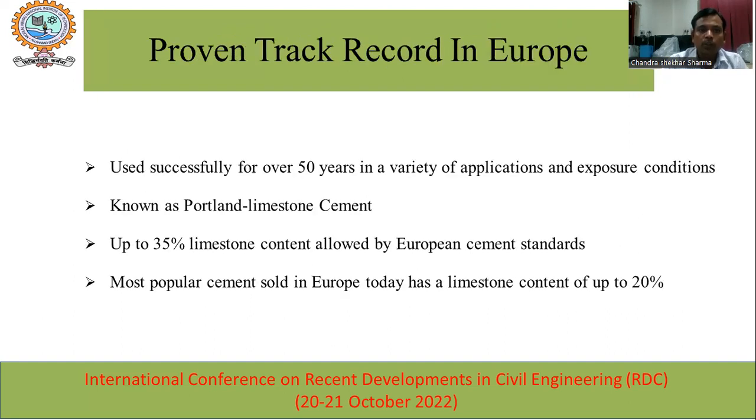Track record in Europe: PLC, known as Portland limestone cement, has been used successfully for over 15 years in a variety of applications and exposure conditions. Up to 35% limestone content is allowed by the European cement standard. The most popular cement sold in Europe today has a limestone content of up to 20%.